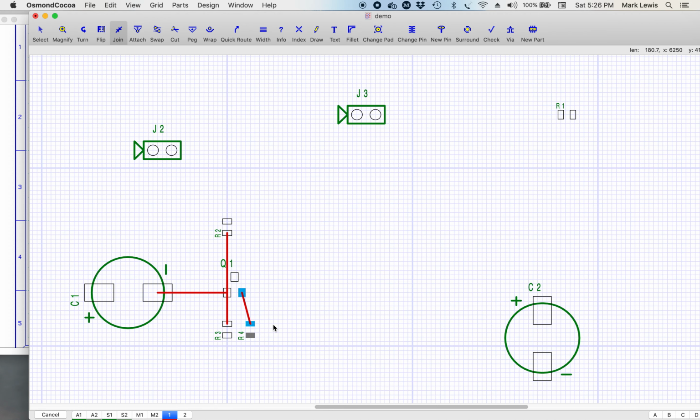And I'll show you a little trick here. What we're going to do is click on the ground side of these. These are all red. These are going to be connected to ground. I'm making a 2-layer circuit board. I can make 6, 8, 12, however many layers I want. But understand that when you start adding layers to a circuit board, the cost starts going up exponentially.